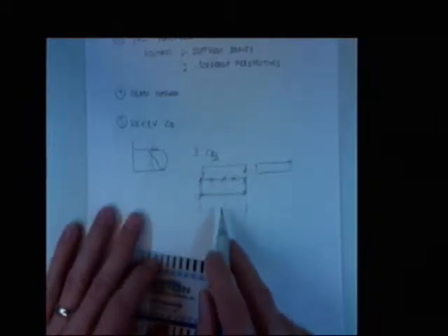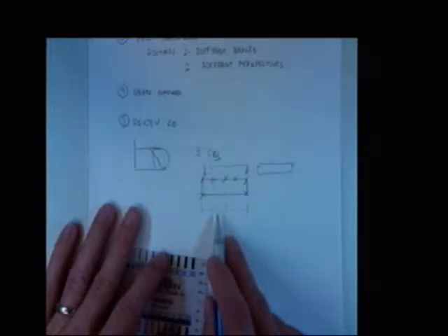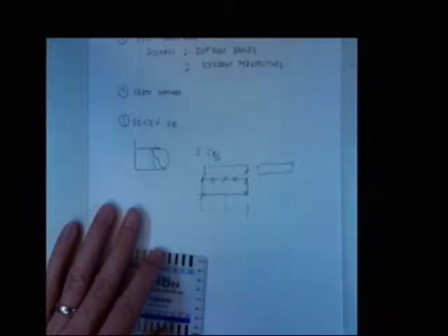These braces do provide us some support at the top, and that now helps us with this C sub B. Notice this C sub B starts at about 3 and then goes down. Okay? It can go up, but it starts at a nominal higher value. You get more benefit from these situations. The C sub B, in effect, helps you deal with these situations and gives you a little bit more capacity.